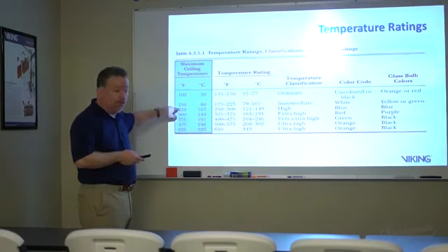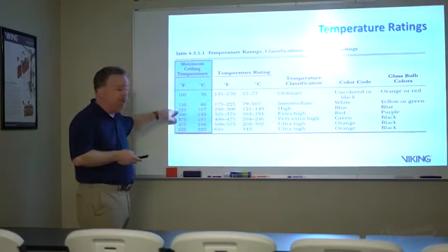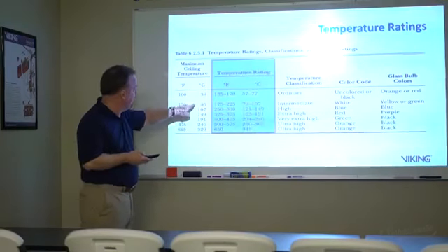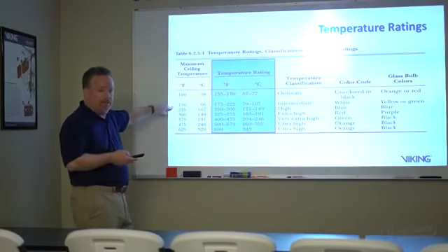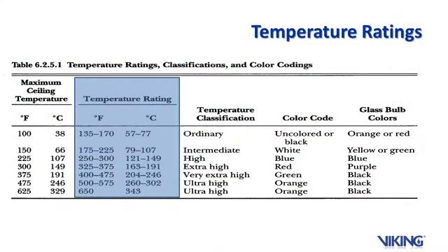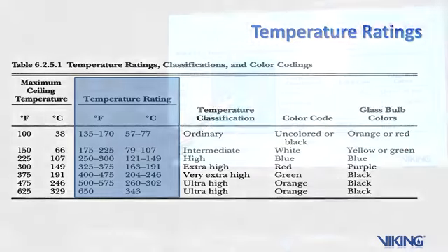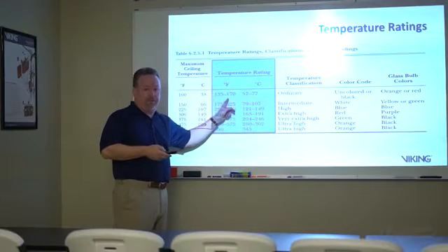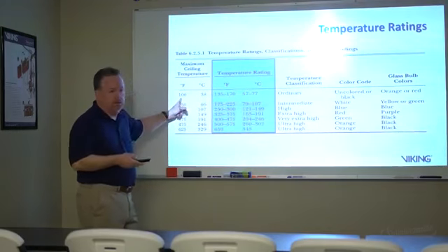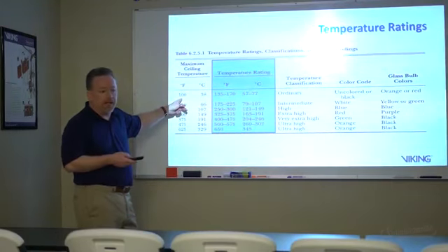easily. So if you've got sprinklers that have to go up there, we need to make sure that the temperature rating of the sprinkler corresponds with what the maximum temperature of the space is going to be. You don't want to be putting these lower 135 to, you don't want to put a 155 degree temperature rated sprinkler in an unventilated attic space. Don't want to do that.